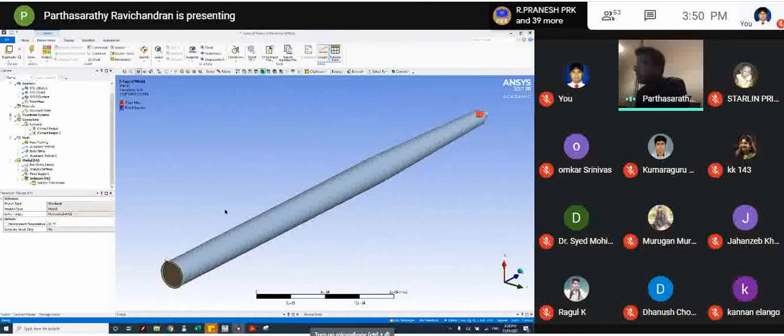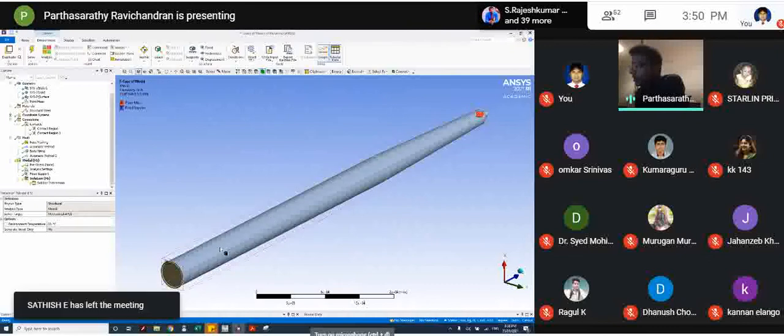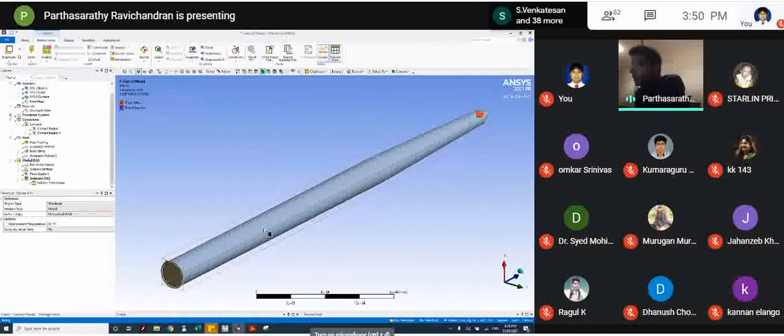So that's another case. In this case, we are restricting the demo to only a lumped mass on the top, a flange at the bottom, and a single material. We are not changing the material to any other materials. We can also do a study by splitting it into three different parts, two steel and one concrete, and check how the results vary. I will be sharing those results with Amos, and he will be able to share them with you. So in this case, let's solve what happens when you add a 30-ton mass on the top.